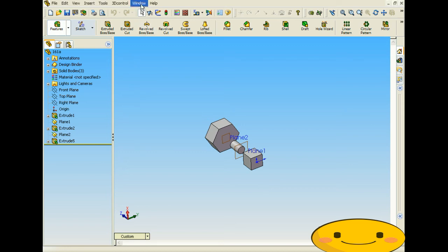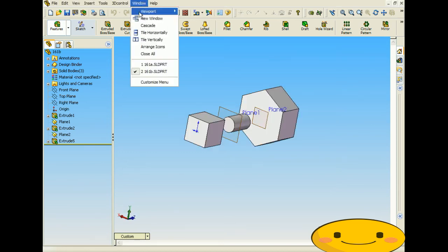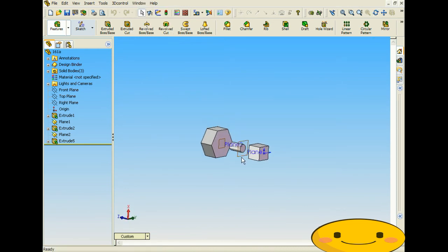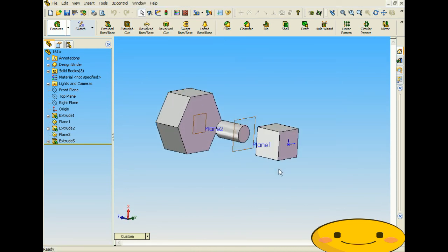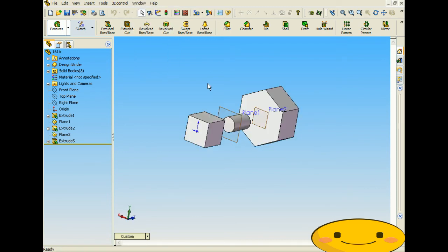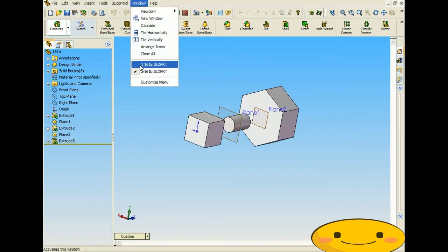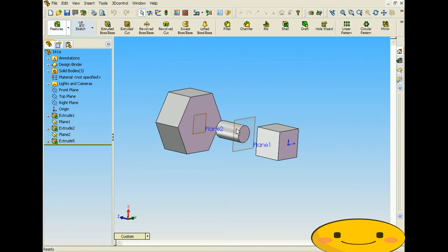Now if you look at the two, they are identical, and what I'm going to show you is that we're able to create a different object by blending three different objects together using the Deform curve-to-curve, but also the sequence in which you put these together will result in a different final product. So I'm going to show you how to mesh three of these together, and then I'm going to show the difference between doing one style. So on 161A, we're going to do one style, and then on 161B, we're going to do another style. So it's just a different order of how we're going through it, and we're going to get a different result.